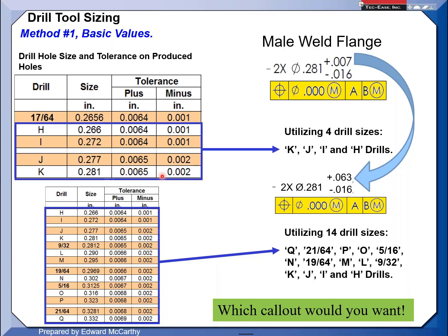It's so easy to do a design and make every feature tightly toleranced. Well, you're going to drive the cost up. And I've heard, "Well, Ed, the process we're going to use is capable." Fine, that's capable, but there are other things that make a part non-compliant: inherent stress buildup, distortion, other things can play in here. Myself, if you look at a lot of my designs, you'll see a lot of zeros. I'm giving manufacturing everything possible to provide me a part that will go together.